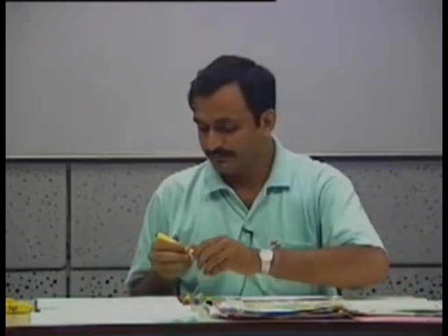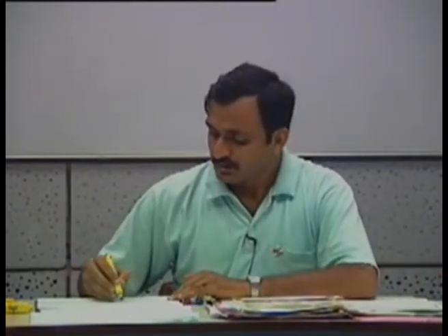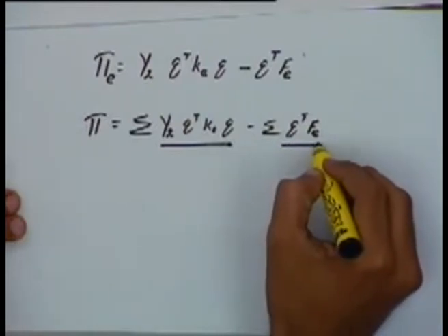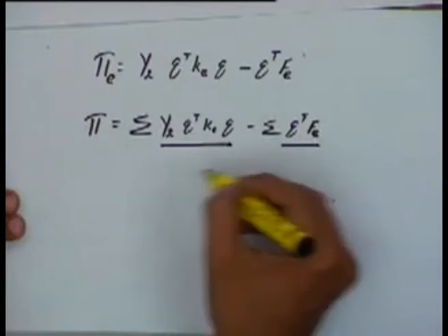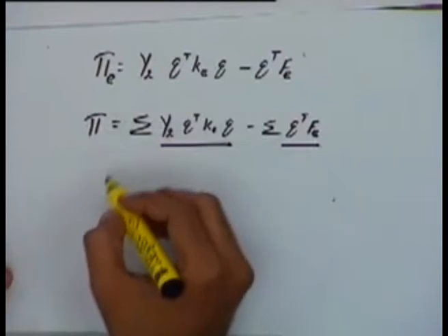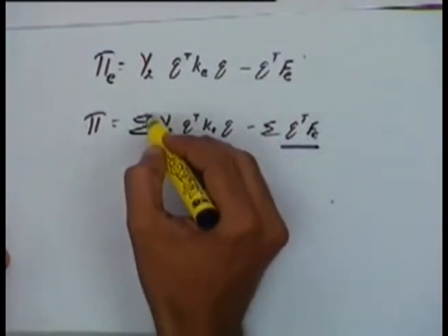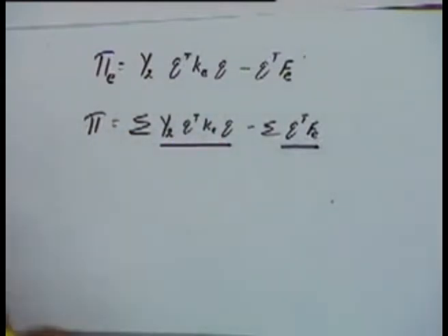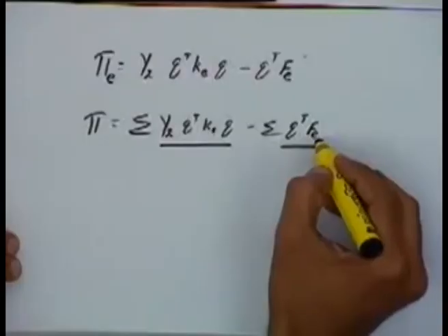Then the next thing is that these expressions are for the potential energy in one single element. Okay. Similarly, this is also for the potential energy contribution in one single element. When I do a summation over all the elements, I can simplify these equations further. Okay, you can get them into one single matrix and then remove the summation. Okay, before going into that, let's take a simple example and see how we can get the KE and FE matrices.